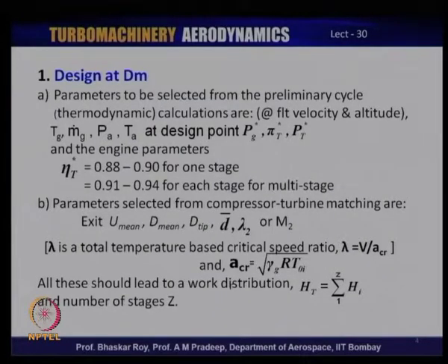So, if a little more work is to be done, that has to be done by those stages, every one of them doing a little more, or a little less work can be redistributed among some of the stages, so that you do not need to reduce or increase the number of stages in the process of design. So, the number of stages is decided by the aggregate amount of work that needs to be done,